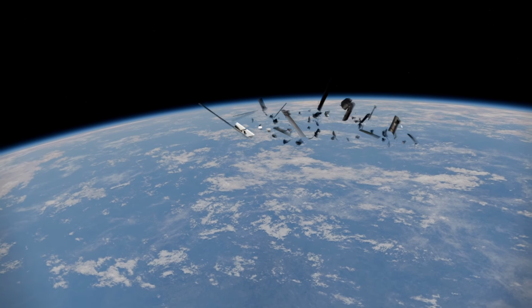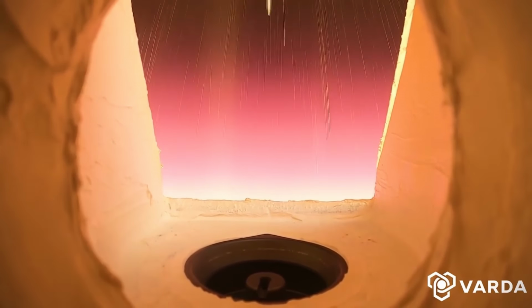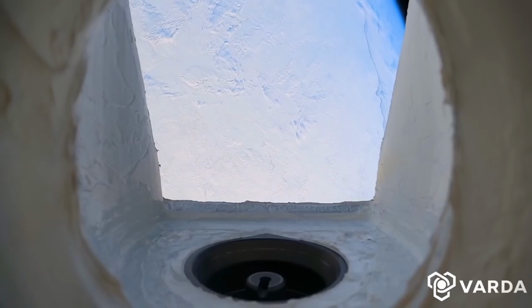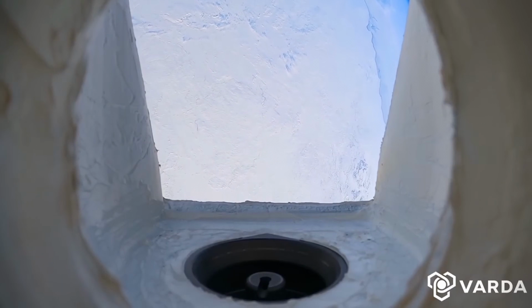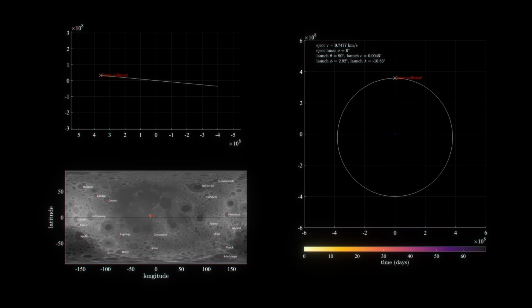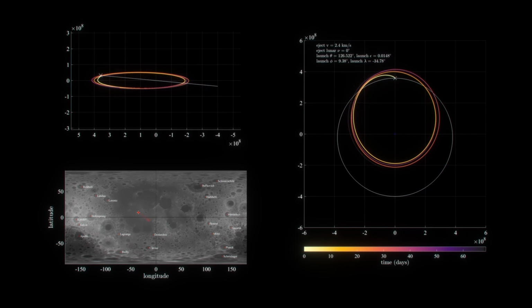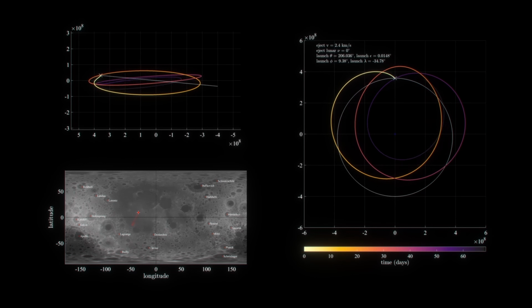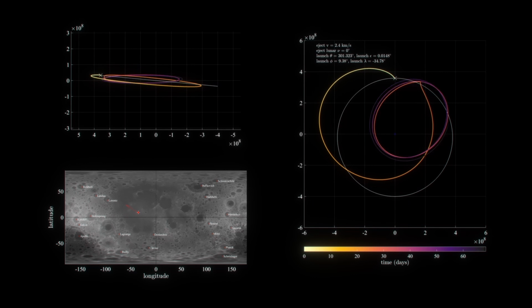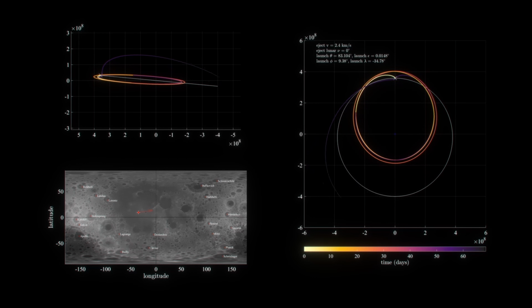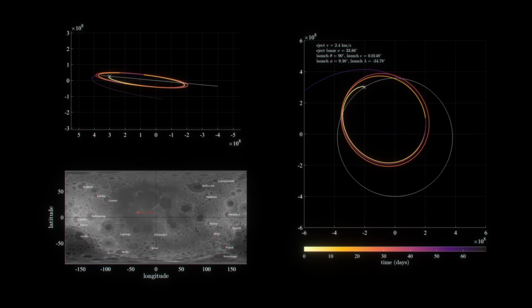We also did not allow for aerobraking. The rocket pods were not allowed to dip below 200 kilometers around Earth, both because skimming the highest thinnest part of the atmosphere is hard to model cleanly, and because accidental deorbiting is not a failure mode we want. The same 200 kilometer exclusion zone was applied around the moon because getting too close introduces extra perturbation messiness from lunar mascons, which induce non-trivial perturbations for the moon as opposed to the Earth because of the moon's much lower gravity.